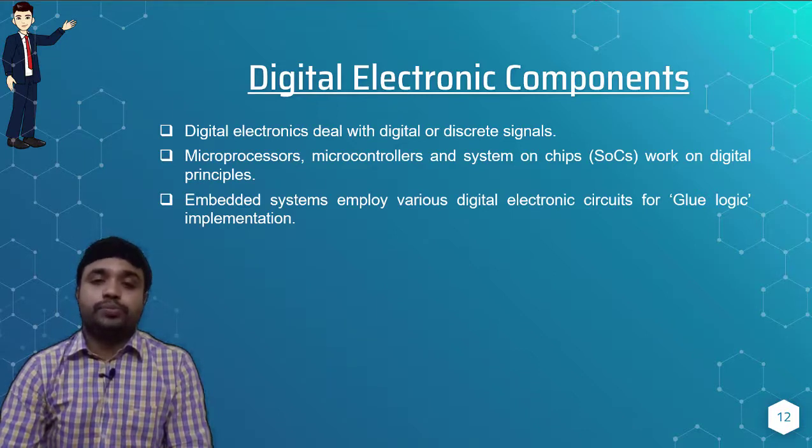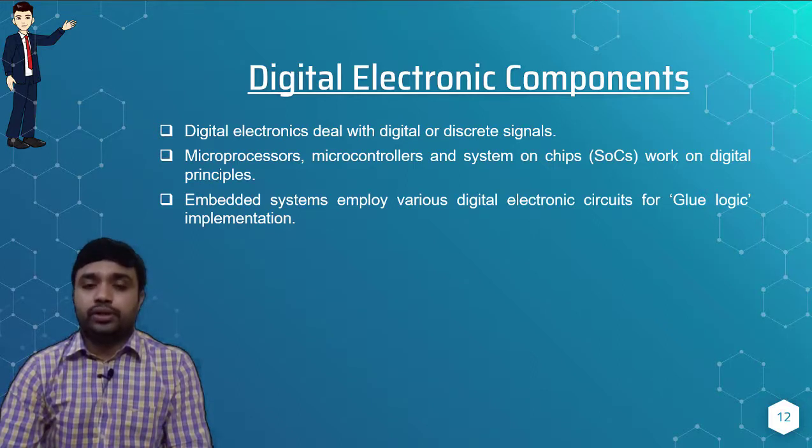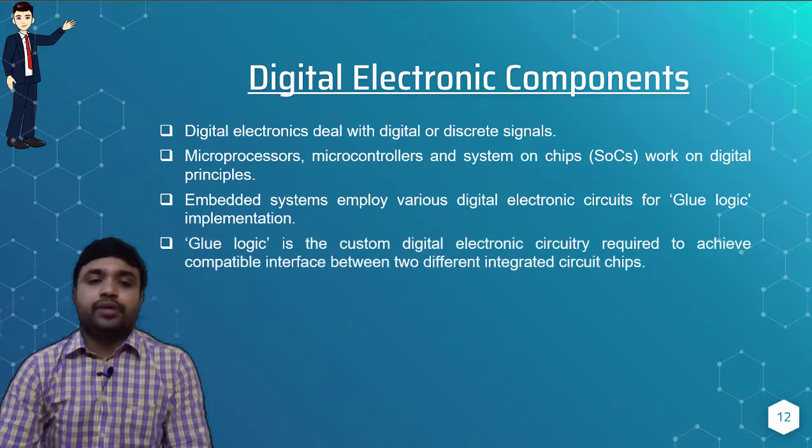I hope you are new to the word glue logic, but I think this glue logic concept is already known to you in your VLSI subject. So what exactly does glue logic mean? The glue logic is the custom digital electronic circuitry required to achieve compatible interface between two different integrated circuit chips.